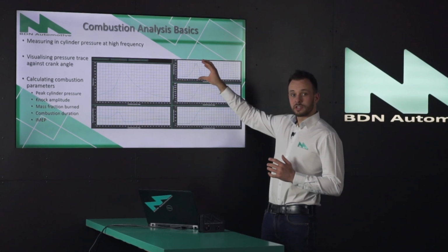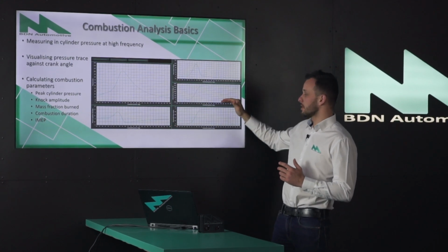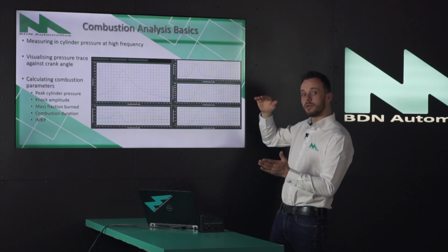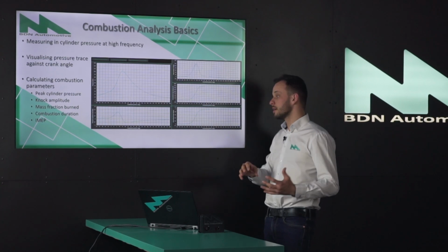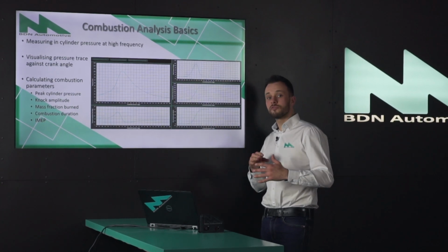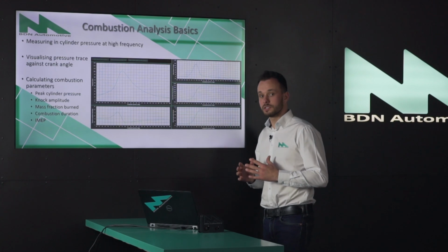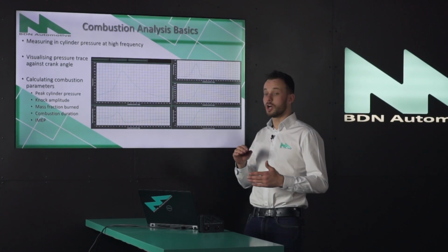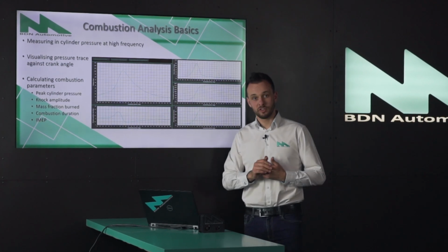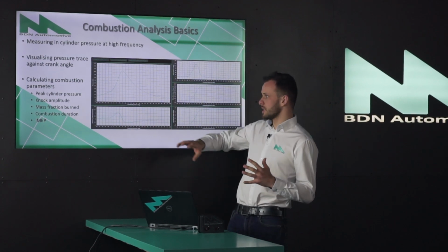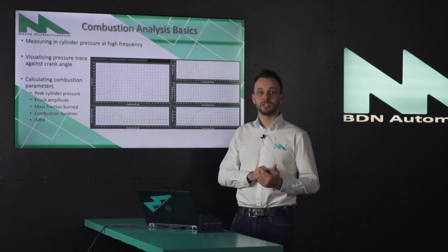If you take a look at the heat release function and cumulate it, normalize it, you will have an S-shaped curve, which is going from 0 to 1. If you take the half of it, which is showing you that 50% of the energy has been released, that is the MFB 50 point. If mass fraction burn 50 is around 8 to 10 degrees after TDC, you will have an optimized engine efficiency and the highest performance. Last but not least, there is the IMEP, indicated mean effective pressure. This is related to the area under the pressure trace and is directly proportional to the engine's output torque.